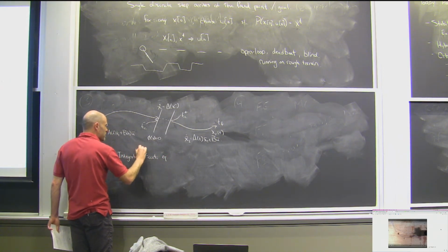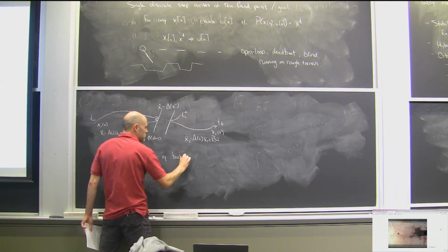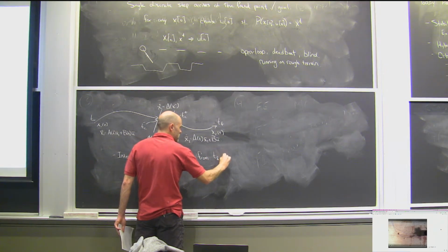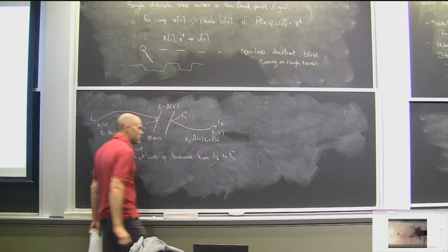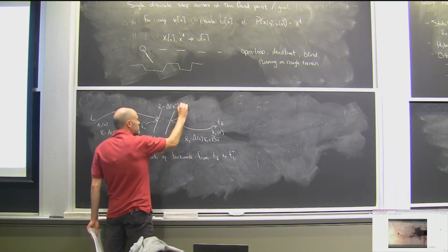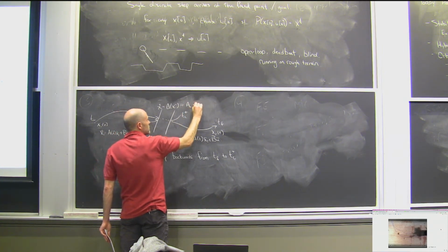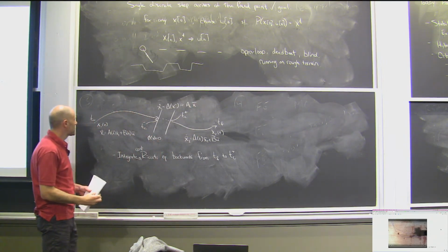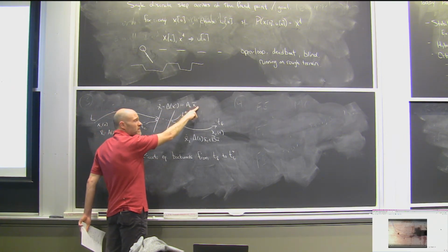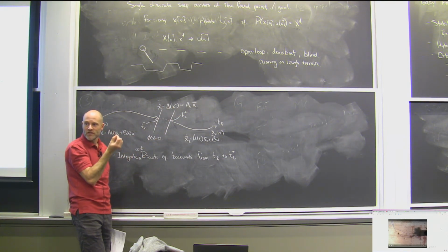This is the continuous differential Riccati equation backwards from T final to TC plus, okay? And then it turns out, if I make another linearization of the collision here as x bar, I could put a control input there, but I often don't because zero time passes there.